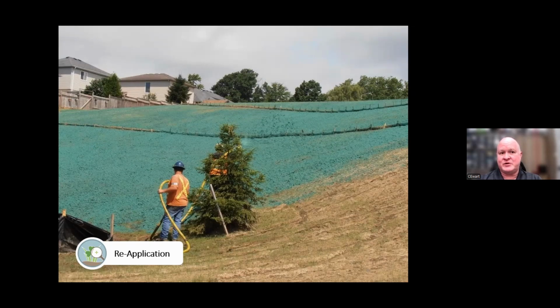That being said, if this were a situation where you were spraying something like a flexible growth medium on here, or you had enough time to establish vegetation before the storm events were coming in and you're irrigating, then it'd be a totally different story. So again, it comes down to that. What is your goal? What have you designed this for? What time of year is it? And what are your chances of getting your vegetation established before the rain comes? Reapplication is always far more expensive than spending a little bit extra money and doing it right in the first place.